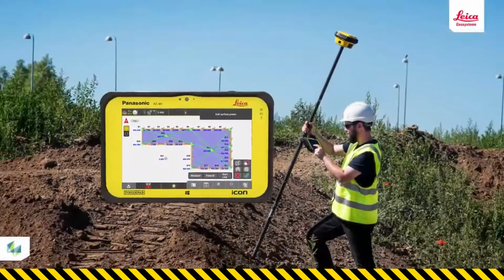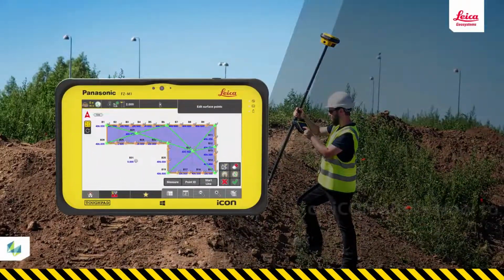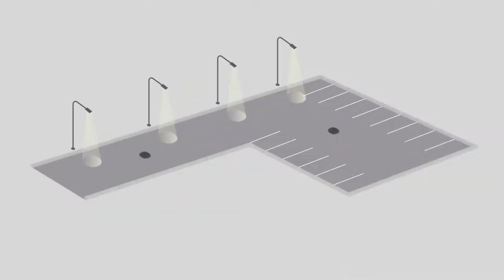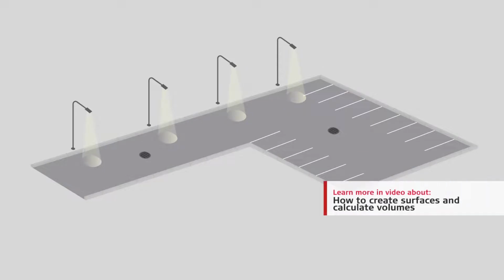In this tutorial, you will learn how to add boundaries and break lines while creating a surface and how to shift it. You will also learn how to add an expansion factor into a volume calculation. In this exercise, we build the next layers of the planned parking lot on the area we leveled out in the video how to create surfaces and calculate volumes.